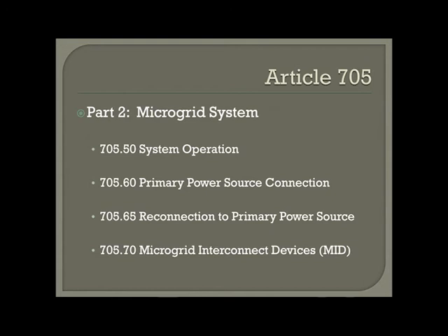And label that. So I go out to look at a system and a conduit's going up the wall and I see the disconnect, but I don't see anything else. Well, is that conduit AC or DC? And it's not marked. Well, you're going to have a violation there and you're going to get a callback because that needs to be identified. But do you have to identify the AC and the DC? I say yes, because I don't know what it is, can't get in the house. So just label it. Photovoltaic system. I think it requires it every 10 feet. So if you don't want to come back and do it because I'm going to require you to, you just as well do it now, all right?